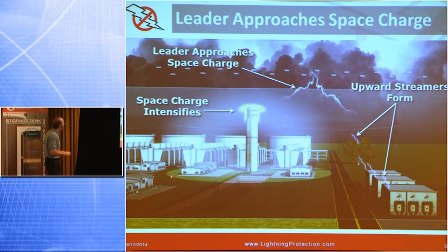What's going to happen now? We've created this space charge. There are three things we don't want to happen to our system or our protected zone. We don't want to have upward generated lightning, an upward leader. We talked about that. If this is a 100-meter tall stack, it could do it. Remember I said that anything over 100 meters could theoretically develop upward lightning. Well, if I keep this potential so low, below the threshold of lightning, I'll never develop it. So I keep those fields below that of lightning. Ground developed lightning is a pretty rare one.